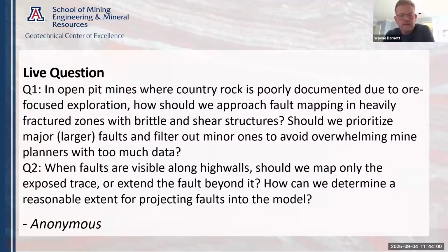Yeah, and that includes looking at your rock mass. Do you get a lot of segmentation on your faults? That gives you an understanding of how far you can project that in your model. In my opinion, in general, I'm going to be more conservative when I build a fault.